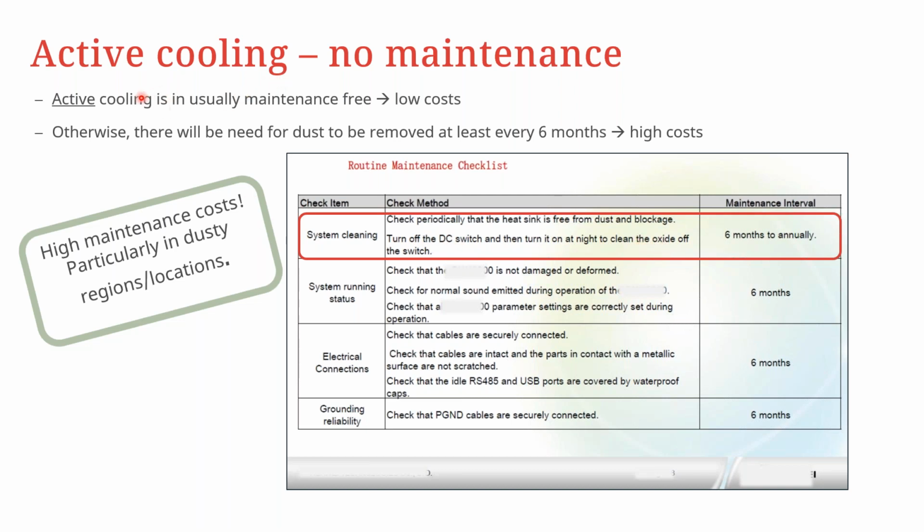But with an actively cooled inverter, the heatsink fins are naturally cleaned by the air that is being pushed out of the inverter by the fan. Therefore, you can see that for a passively cooled device, you're going to have higher maintenance costs, particularly in dusty regions or locations.